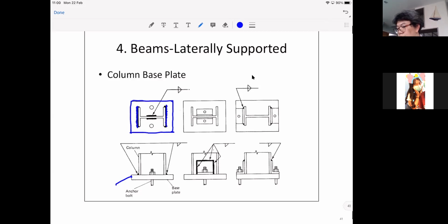And then with the anchor installed before, you can just put the plate that is already attached to the column in here, and then readjust the level by using the screw to turn, and you will have the installation of the column. And just like the previous case with the beam, the size of the base plate will help prevent the concrete crushing. So you know the load of the column, and you calculate the size of the plate big enough to prevent the concrete crushing.